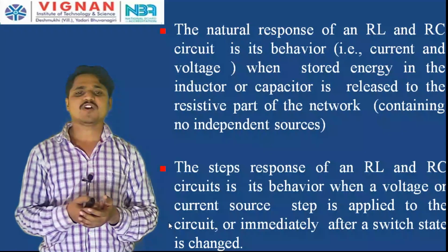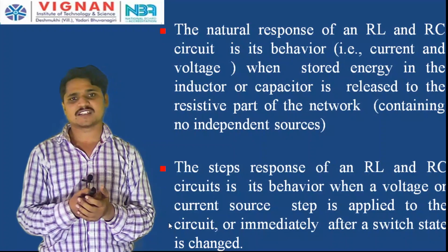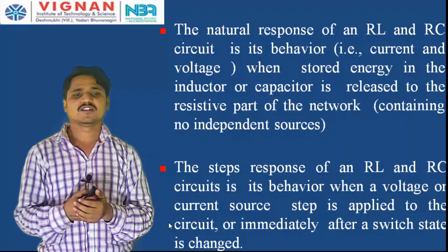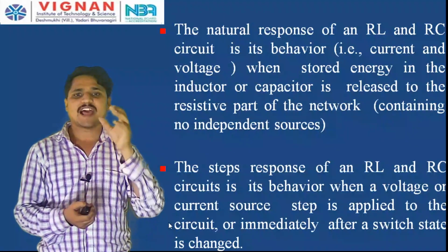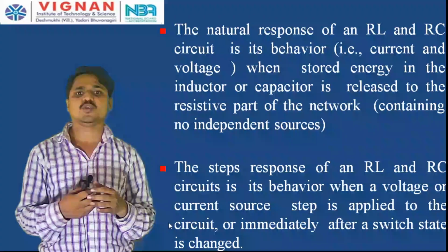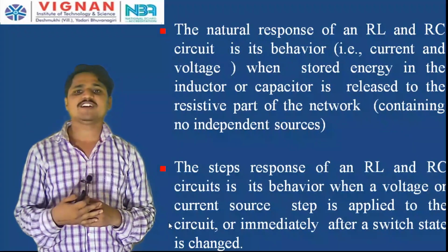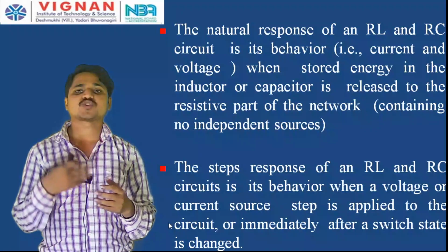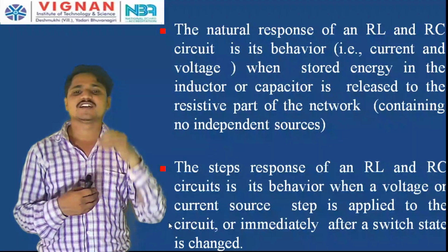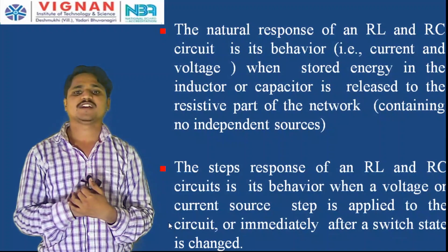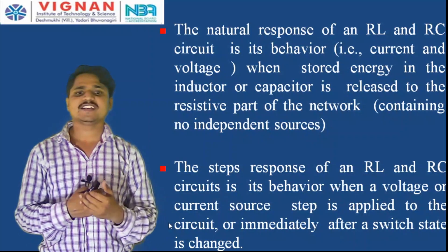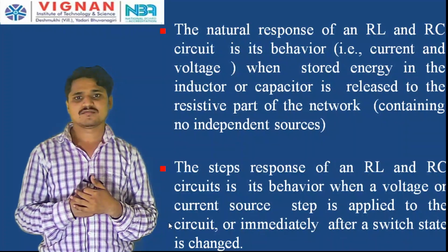Response means whether you have to find the voltage across the inductor or the current flowing through the capacitor, whatever it may be. So, the natural response of an RL and RC circuit is its behavior when the energy stored in the inductor or capacitor is released to the resistive part of the network, which contains no independent sources.